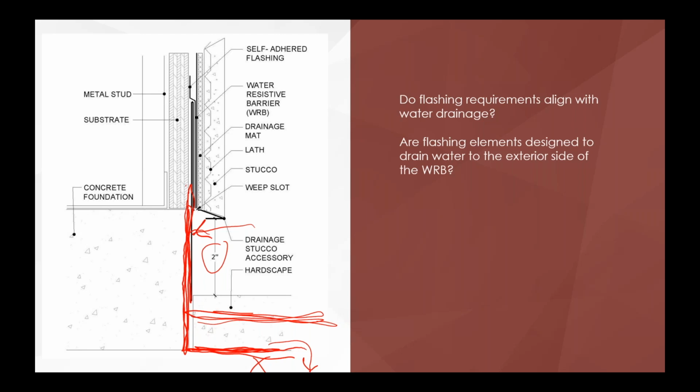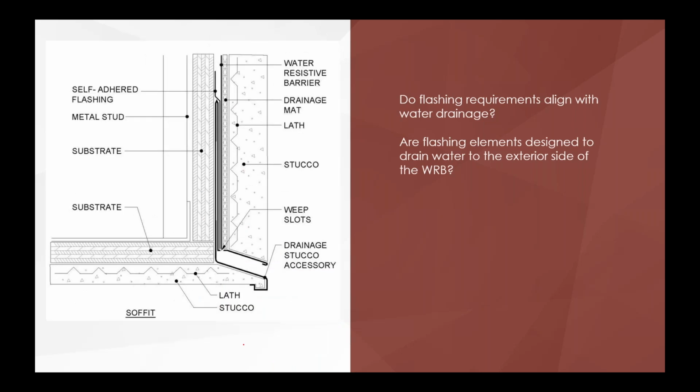But I do think it's a good point that a stucco contractor could be tied into this, when it really had nothing to do with it. Their work started above here. The waterproofing was down here. So they're two separate trades. But again, this is why pre-con is so important, to bridge these types of gaps. Again, back to the stucco one, I won't go on much here because we've talked about it before, but your common goal when you're looking at that detail is: okay, I've got my water here. Where's my exit? Oh, I've got an exit here, I've got an exit here, and there's no way for water to get back here. That's our goal. As long as your detail does that, you're fine.